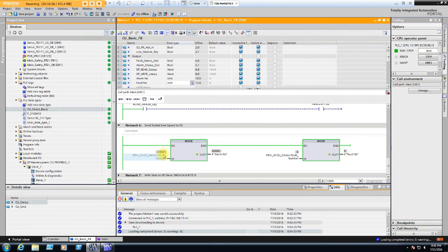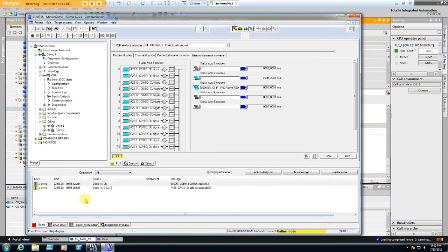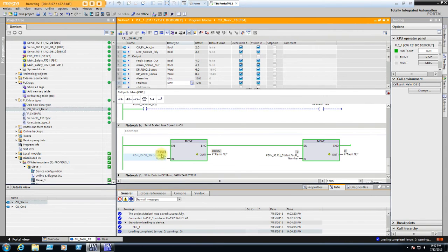So you get this, and you're like, well, that number doesn't match what the drive says at all, right? It's like, well, this thing says 50,005, and this says minus 15,000. Wow, that's crazy. Well, what you've got to do is define it in the data structure, which probably I should change just to make stuff look good as well, to be an unsigned int.